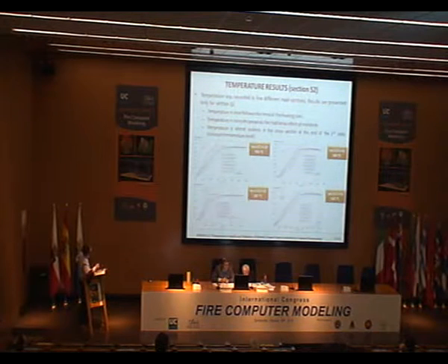The temperature in steel follows the trend of the heating rate, a constant trend of 800 degrees per hour, and the temperature in concrete presents the traditional effect of moisture, and temperature is almost uniform on the cross section, as you can see.